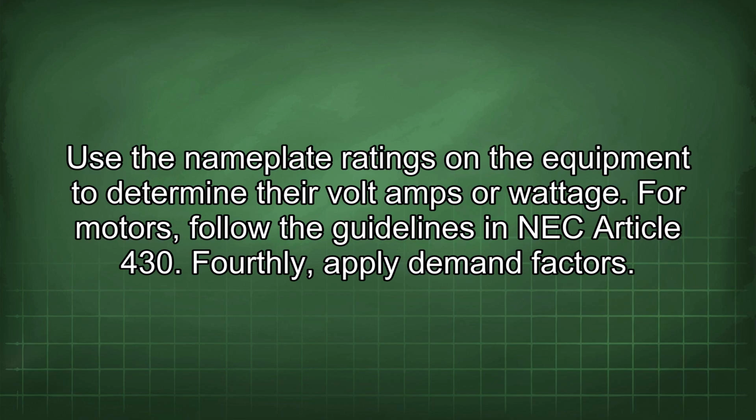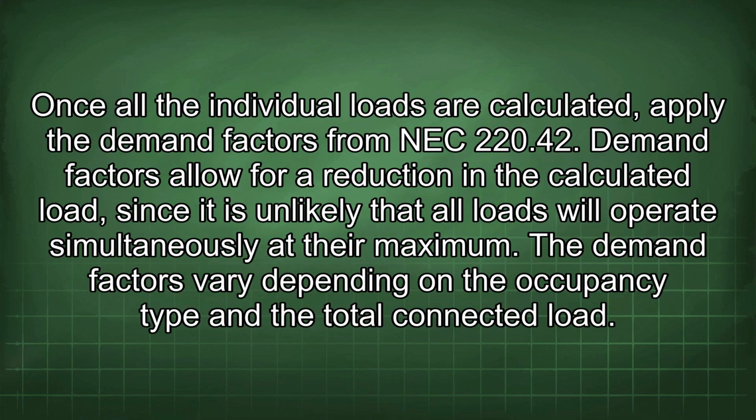Fourthly, apply demand factors. Once all the individual loads are calculated, apply the demand factors from NEC 220.42.